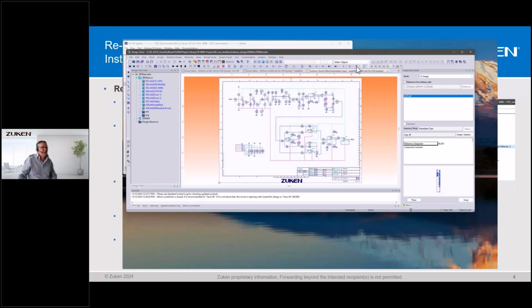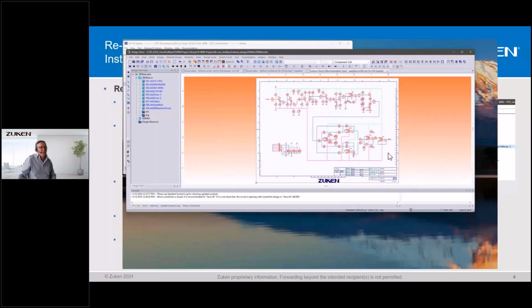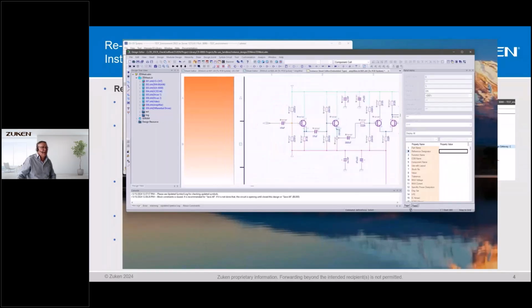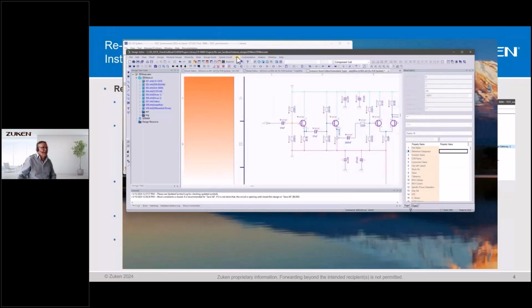So we can see on the top left, we are in the instance sheet. And you see, of course, we have all the old reference designators. As I said, I want to get that renumbered. I delete all the existing reference designators by that functionality. You see no reference designators any longer. I set a sheet property saying the initial value for that sheet should be 800. And after that, we simply rerun the reference allocator on all open parts, all open gates.